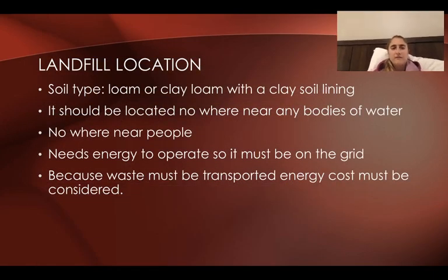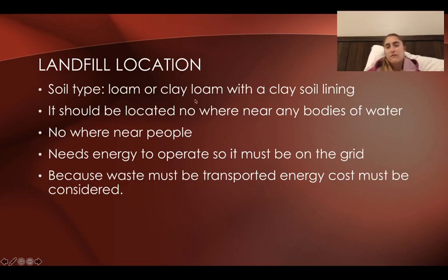Okay, so where are landfills located? Location is actually really important. So first you have to look for an area that has a loam or clay loam type of soil, where you can put a clay soil lining in it. So the type of soil will be an important component to where a landfill goes. This is sort of the ideal. It shouldn't be located anywhere near any body of water where potential leachate can get in and pollute it. It shouldn't be anywhere near people, again, potentially if that leachate gets out, or the smell, things like that.